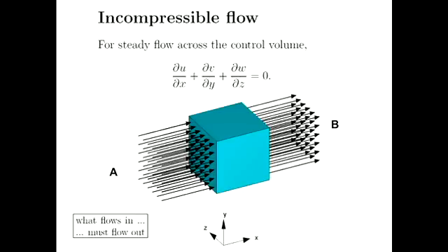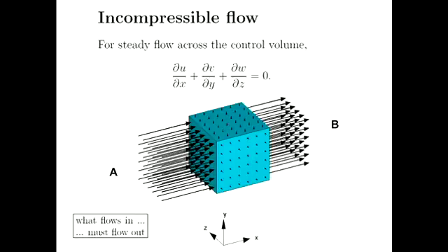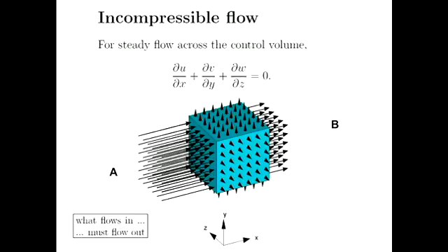So now, if I somehow obstruct that flow of fluid coming out through control surface B, say I put my hand there, or my face there, or say it was the nose cone of an aircraft or a rocket, or the front of a building or a wind turbine, that equation just tells me that if there's less mass flux coming out through control surface B, and there's the same mass flux going in through control surface A, that flow just has to squirrel out the sides, okay? That makes perfect sense. And that's very intuitive, right? You know that's how fluids behave.